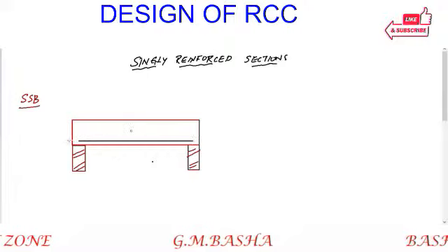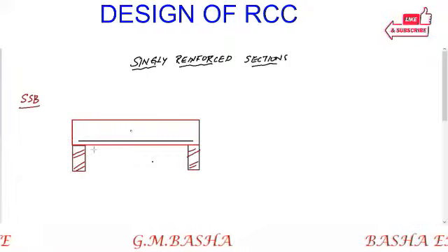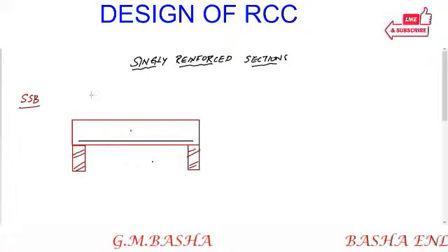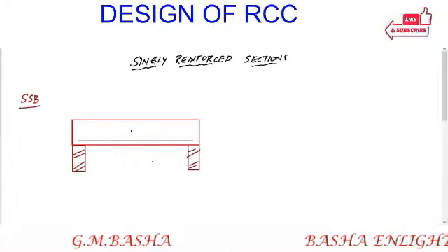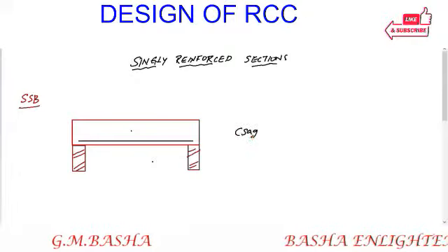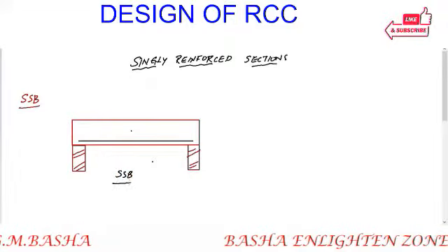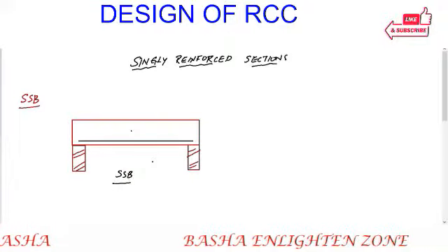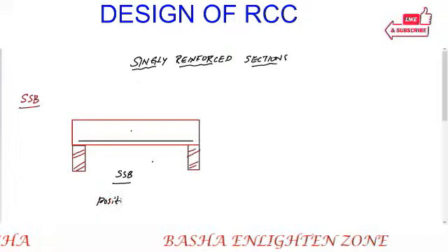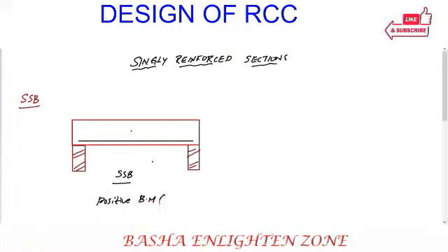So for simply supported beams, tensile stresses are induced in bottom layers because of positive bending moment, that is sagging bending moment.